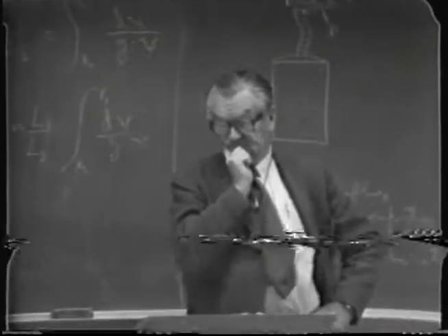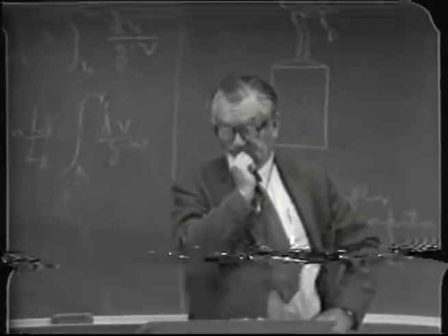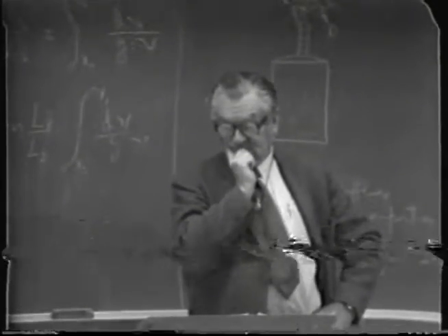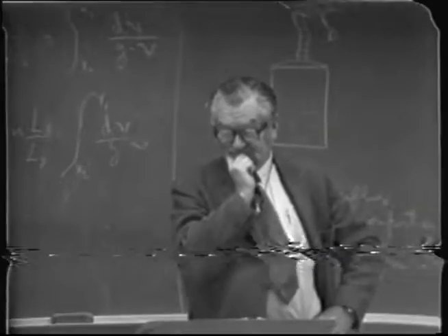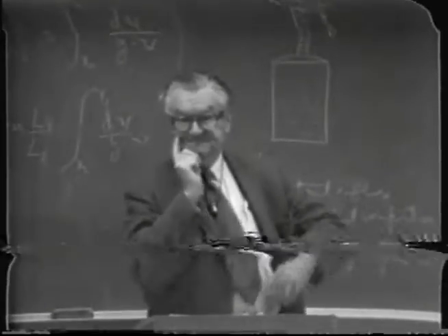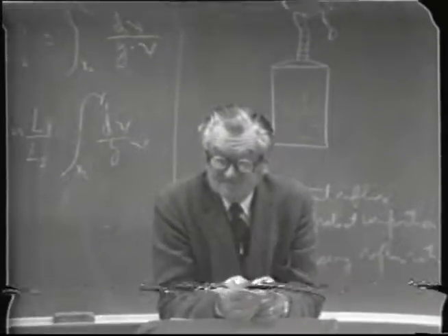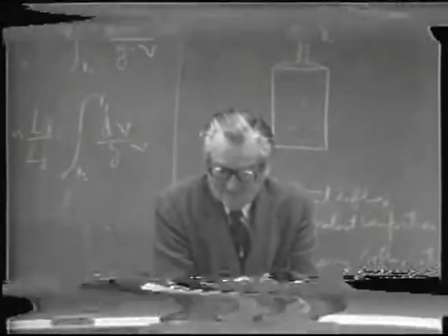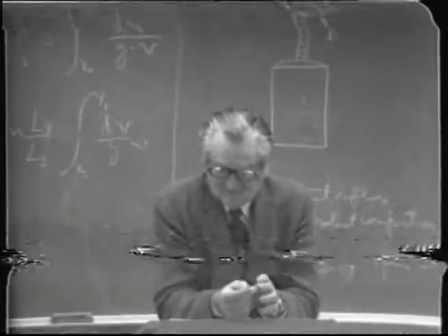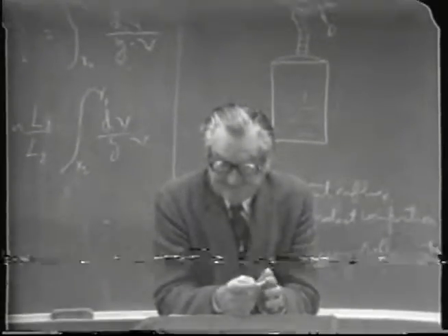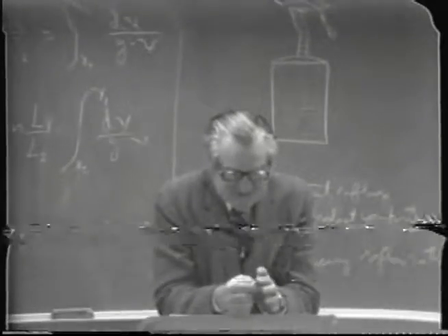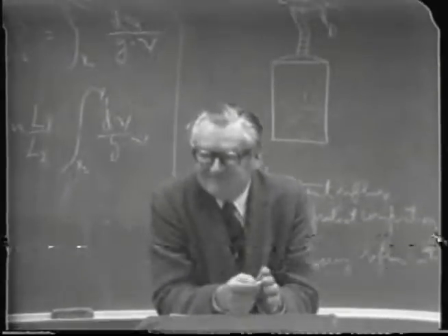You said that if we were given the X of D and the number of ideal steps, and we wanted to find the minimum amount of alcohol in the liquid, then we wouldn't use an operating line, and the ideal steps would be drawn from the intersect on the diagonal to the equilibrium curve, and then right back down to the diagonal. Yeah. There's no operating line in that case. Well, the diagonal, or total reflux, becomes the operating line as the limit.